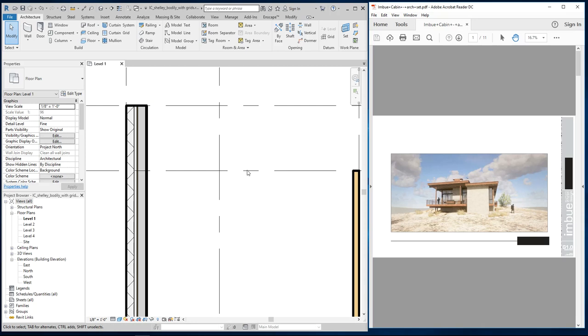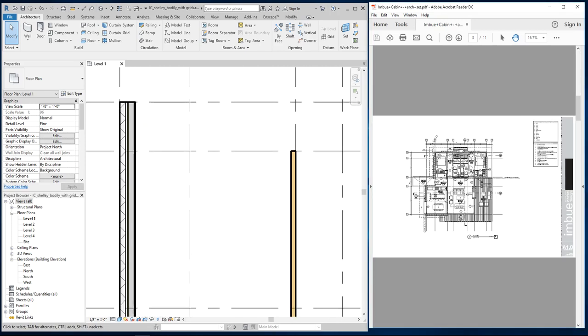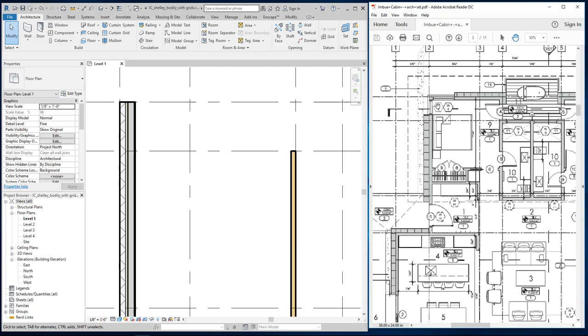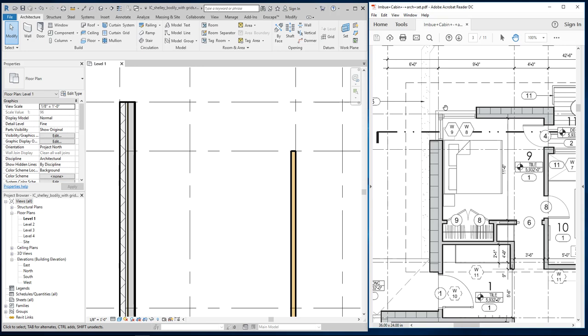Okay, so let's talk about walls today. And I specifically want to create a couple of new wall types just to go over it again. And then I want to talk about how you can take the walls that you generate for your assignment and change them to the new wall types that you generate, okay? Then I'll show you how to place doors and windows. And finally, we'll talk about how to load doors and windows into the project. So different types, right? If the right type isn't in your project.